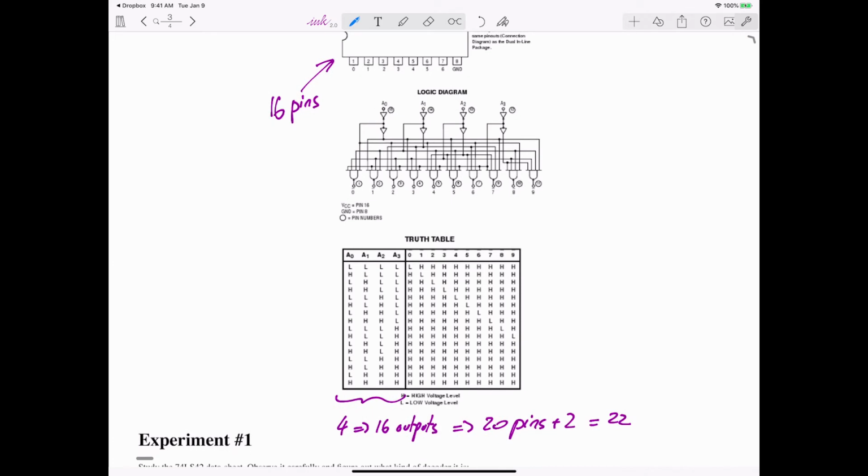So what they decided to do is to decode only partly. In this table, for all these combinations of inputs that I have here, nothing happens with the output. These inputs, low, high, we're not going to be able to decode that. So the decoder decodes only partly. This is 0 in binary, and this is 9. So it's a decimal decoder. It understands only the index at the input that is between 0 and 9 in binary.